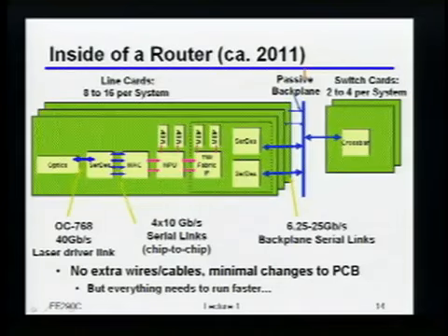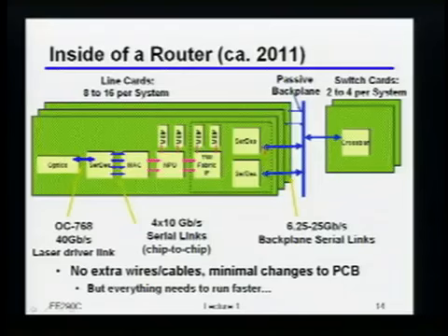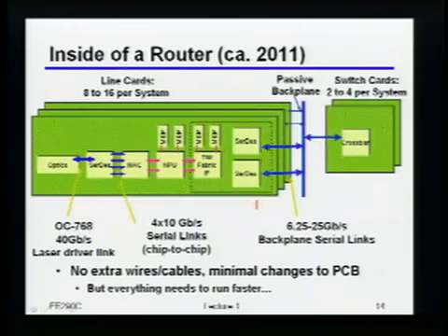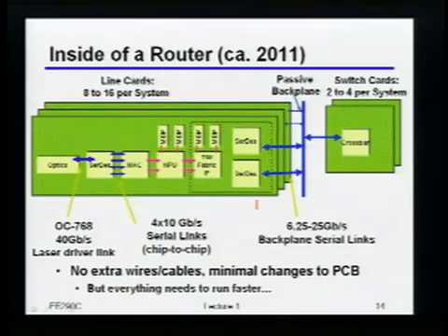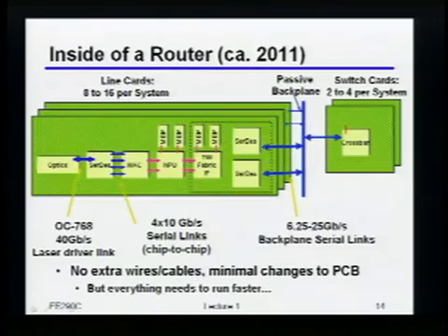Yeah? Another one. So what's the typical power breakdown inside the line card? Okay, that's a great question. I think it's about 50-50 in terms of I/O versus processing and memory, ballpark. Obviously the exact numbers heavily depend upon what exactly you're implementing, quality of service and things like that. But ballpark, about 50% of it is the I/O, and maybe 50% is just talking to these DRAMs, doing this network processing, doing these huge crossbars, and so on and so forth.